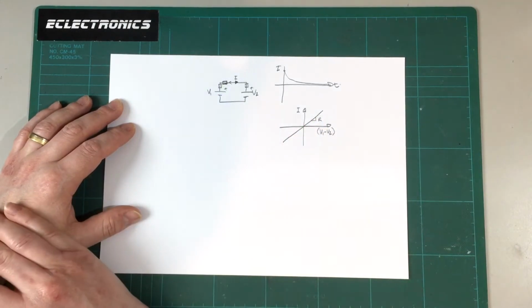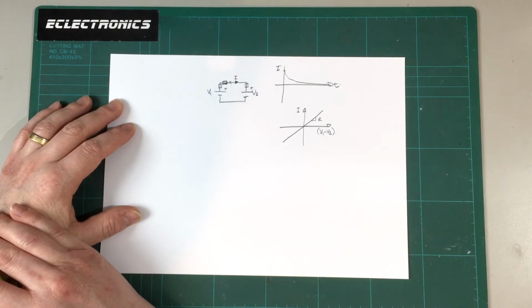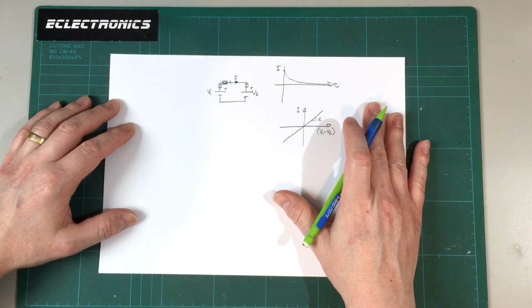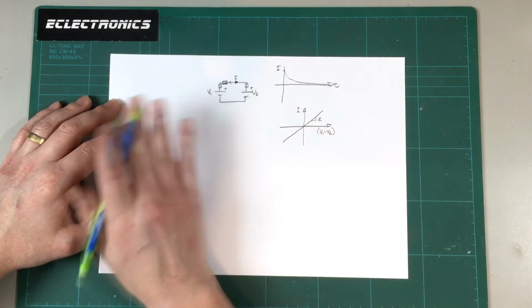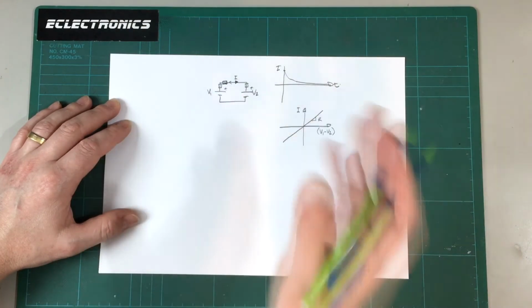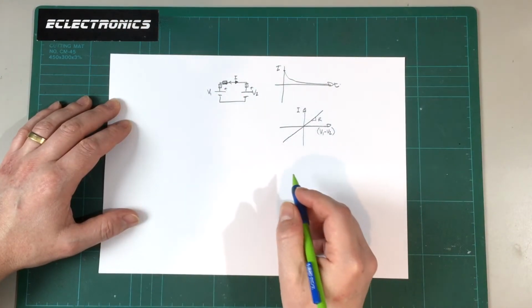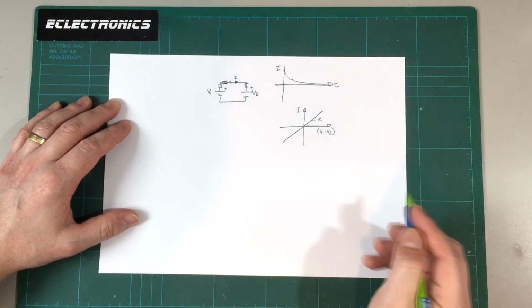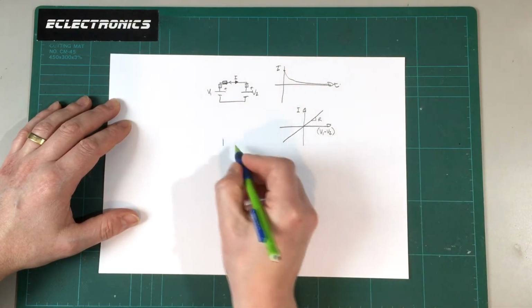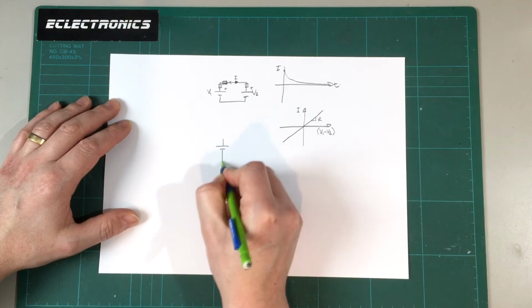It would just be that of a resistor. So that's fairly simple. I think that's relatively easy to understand, but of course in reality we can't balance cells like this. We don't tend to want to take our packs apart, rearrange them so all the cells are in parallel, and then when we want to use them rearrange them all back into series again. So of course what we're more interested in is the active balancers that you can get nowadays.